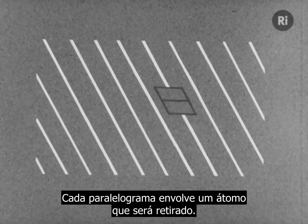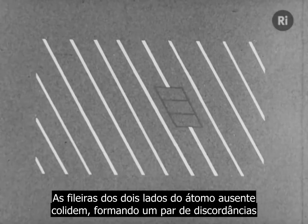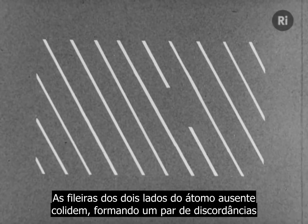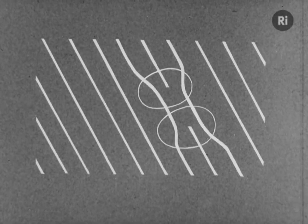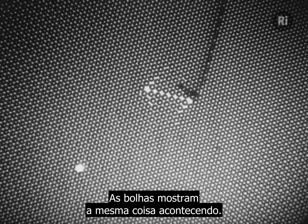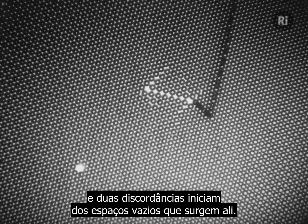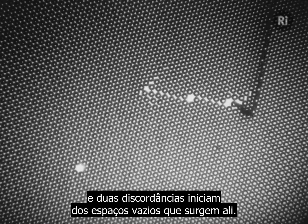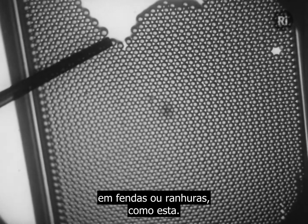Each parallelogram encloses an atom which is going to be taken away. The rows on either side of the missing atoms collapse together to make a pair of dislocations. The bubbles show the same thing happening. A few bubbles are burst with a hot wire, and two dislocations start from the holes so created. Dislocations are most likely to start where the stress is greatest, at cracks or notches, like this.